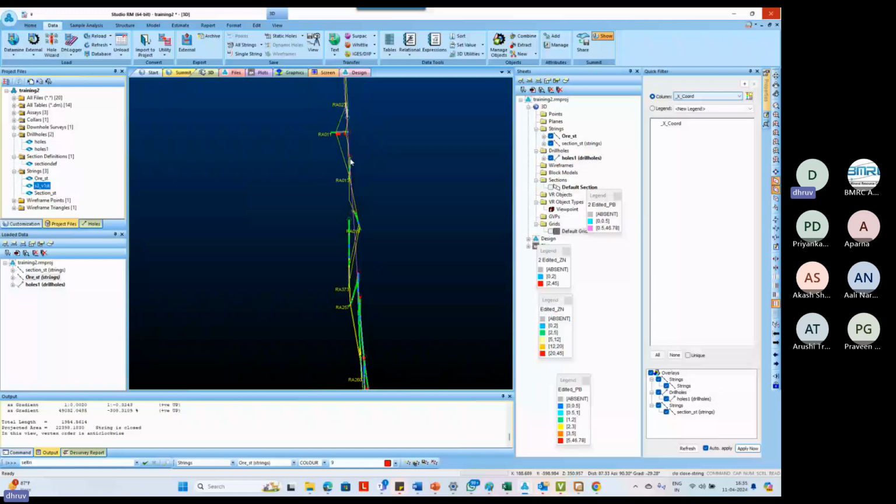But if you have increased your section width and you have used a 100-meter interval and you have snapped on sections 100 meters apart as intersections as well, then this kink would have created a lot of problems. But you have to snap. So what we can do is